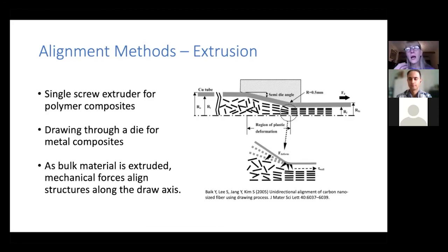But, for example, as we cite in the paper, with carbon nanotubes embedded in copper composites, you get multiple improvements. You get a factor of 2 or more increase in the strength of the composite compared to the material without the reinforcing carbon nanotubes.